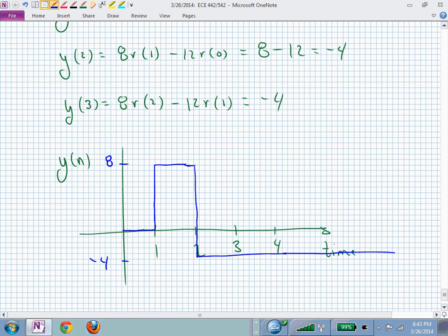Maybe it's not acceptable. Maybe we might want to do something else, but we can now at least stabilize the system. And we did it with, what? The design method via Ragazzini. So this gave us a way to start. Maybe this isn't how we want to always be designing our controllers, but it does give us this deadbeat response, and it does stabilize the system.